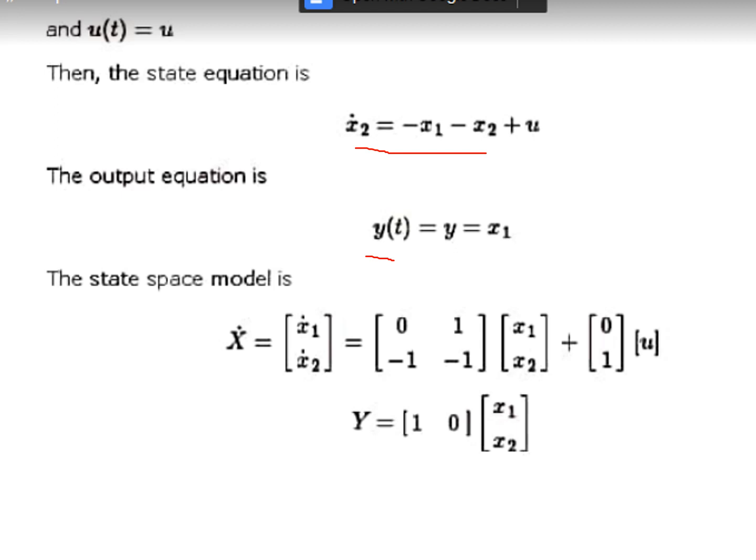By using the x2 dot equation, x1 dot equation and y(t) equation, we form the state model for the given transfer function: [x1 dot, x2 dot] equals this matrix A times x plus this matrix B times u, this is matrix C, and matrix D becomes 0. Why? Because here there is no direct input term.